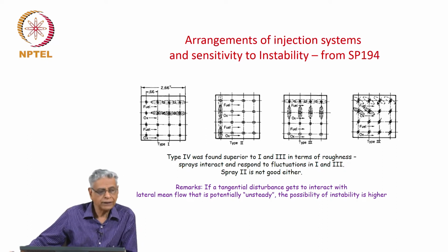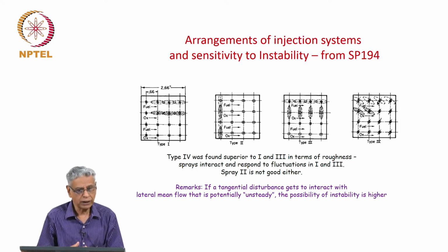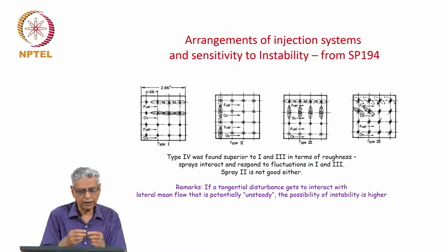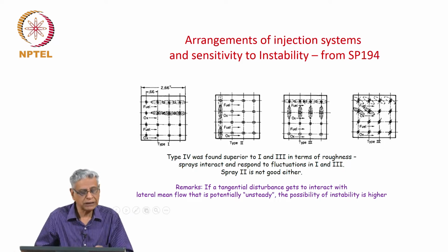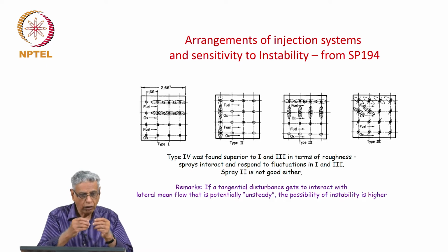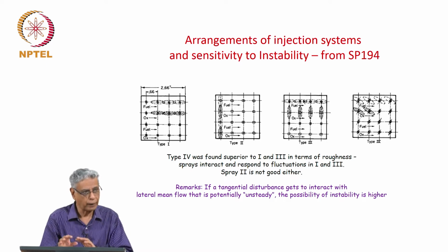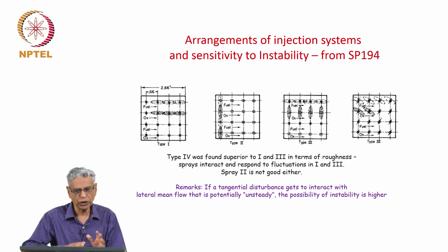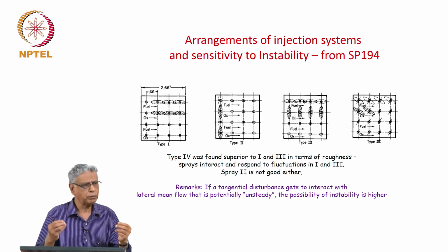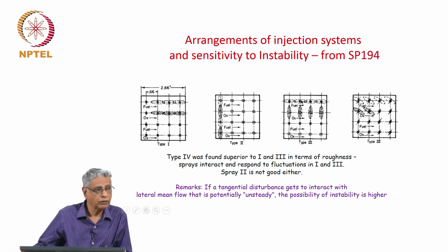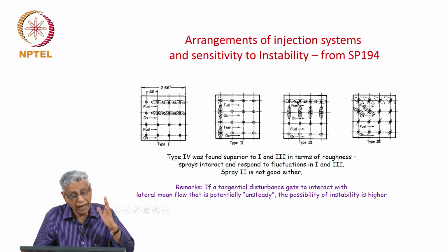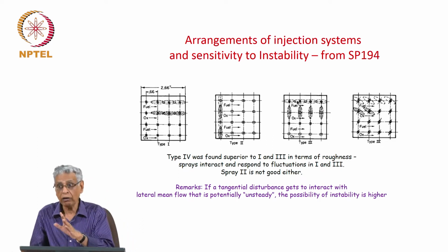The reason is that when the impinging action takes place, the heat release occurs downstream, 30 to 50 diameters of the injector hole, and in that zone you will see the spray fan, which means in this domain you will find fine oxidizer and fuel droplets floating around. Now, when there is an acoustic fluctuation, which is present all the time because of disturbances in turbulence and so on, they have an opportunity to interact with the heat release which takes place because of the droplets, and the main heat release distribution is affected by oscillations.